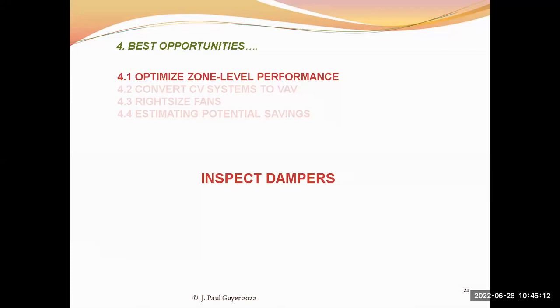And it's these dampers that frequently can get bent, stuck, and so on and so forth. So inspecting the dampers is something that should be done as a matter of routine.